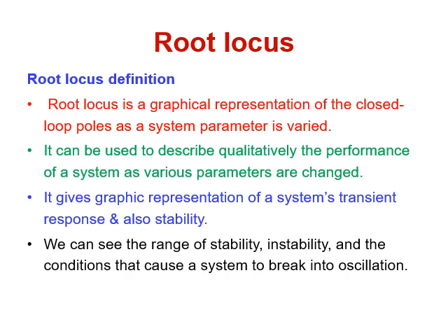Root locus is a graphical way to show us the movement of poles over the S-plane as the gain of the transfer function changes. We will see this in the example on the next slide. It shows us how a change of the gain will affect the pole location on the S-plane.